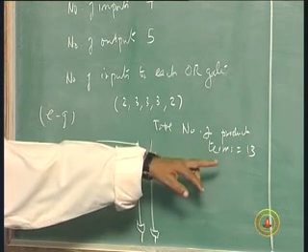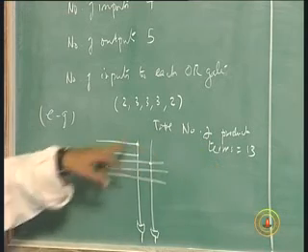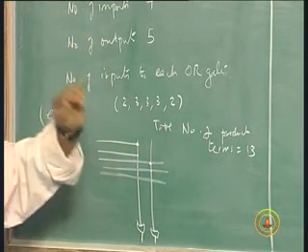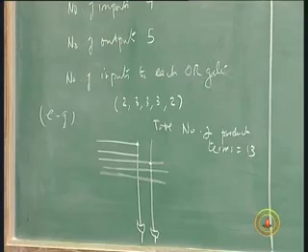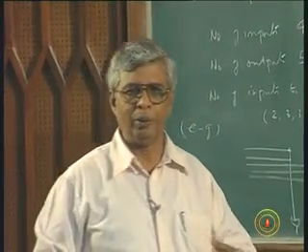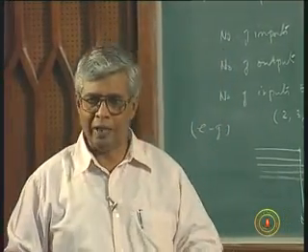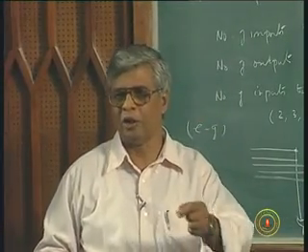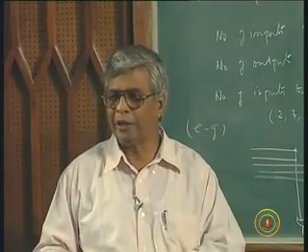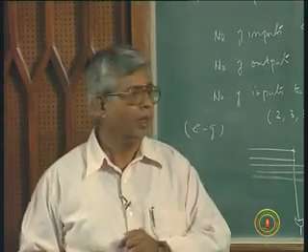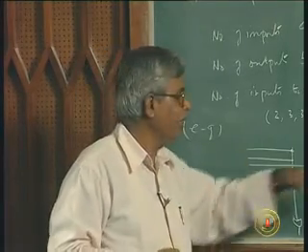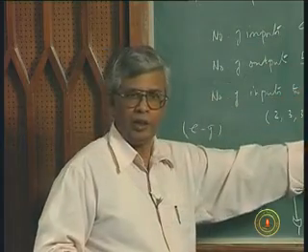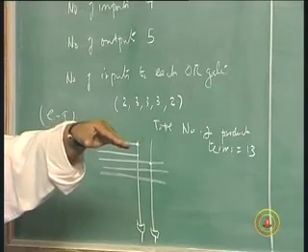There is no use giving this unless you know this structure. That is what I am saying. No use telling you that I have 4 inputs, 5 outputs and 13 product terms. You just minimize it. Use it to get an implementation. Next question you will ask me is, how are these 13 product terms connected to the different OR gates? If I don't tell you that, there is no way you can change those connections. Whereas in a PLA, this is enough. So I can reuse them in different OR gates, right?